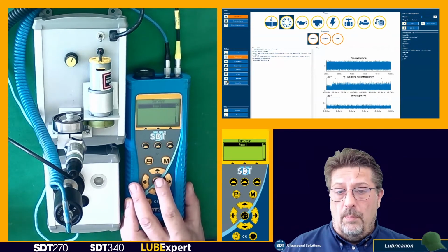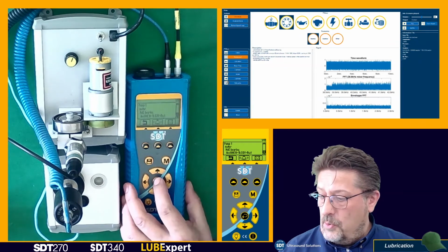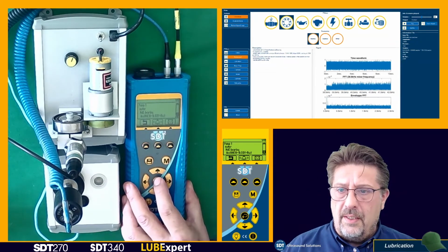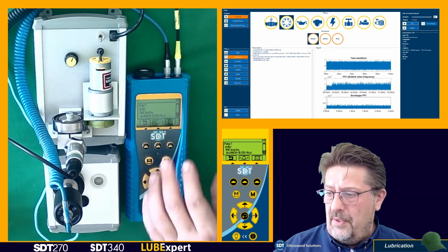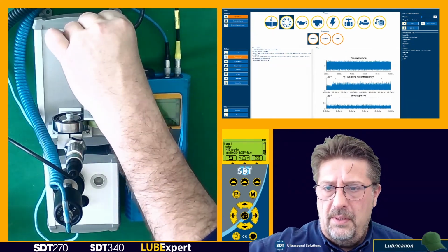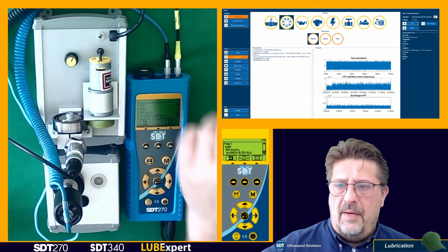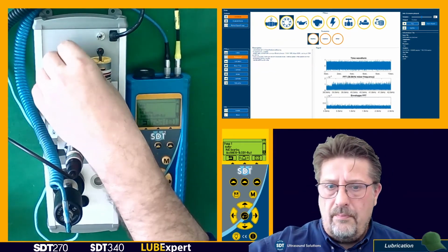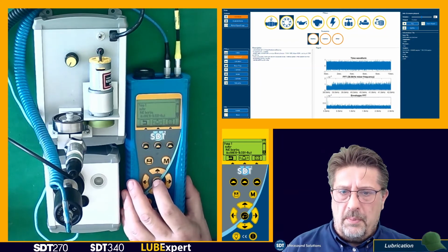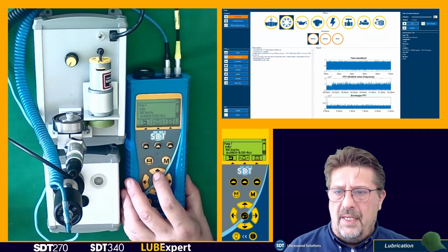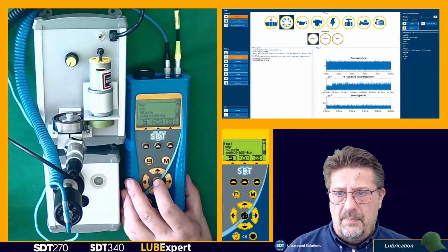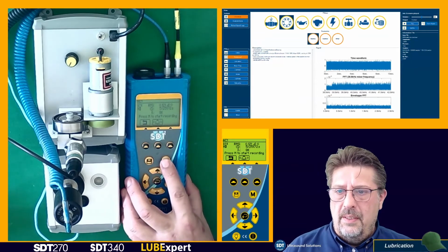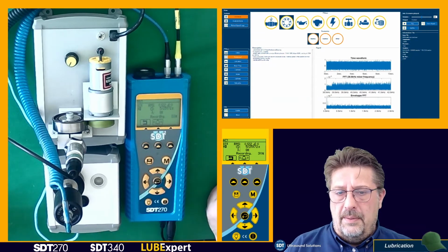We have our pump 1 plant survey as we prepared, and now we have motor, non-drive end bearing, acceleration. Now I will have to make some noise and we will take the measurement. As you can see on the screen, I'm taking a dynamic measurement. Now I enter the measurement and take it.